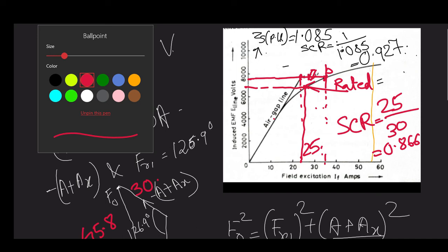Anyway, now coming to the last part of the problem, for power factor 0.5 lagging and 0.5 leading, these are the two extreme cases. Determine the range of field current by ASA method for rated terminal voltage at full load with power factor varying from 0.5 lag to 0.5 lead.